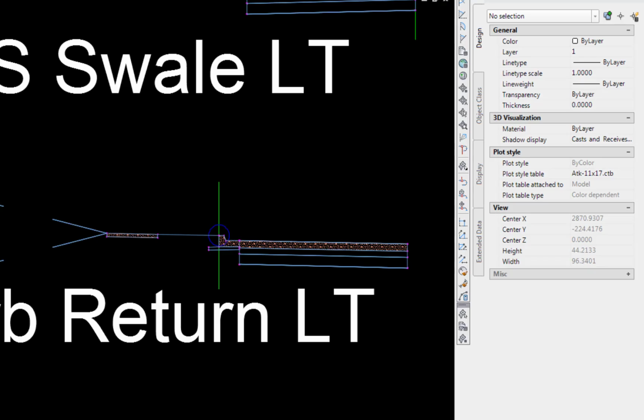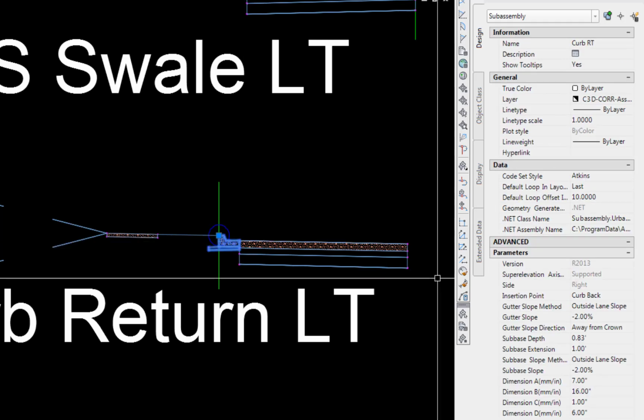Okay. Modify the curb and lane parameters in the left curb return assembly to reflect a 1 inch wide gutter and a 5 foot lane width with inside width extensions and correct slope. The appearance of the curb and lane will change as each parameter is modified. Modify the curb parameters. Pick the curb subassembly.